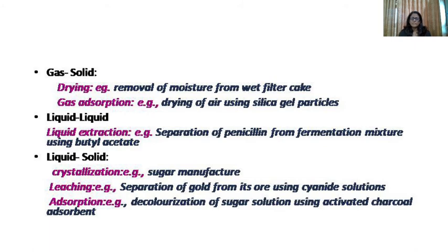Coming to leaching, which is also known as solid extraction, it is an operation which involves the separation of components of a solid mixture by contacting it with a suitable immiscible liquid solvent. The solvent selected dissolves the particular component from the solid mixture which needs to be separated. That is how separation is achieved in leaching. For example, many minerals occurring in nature are not in pure form.